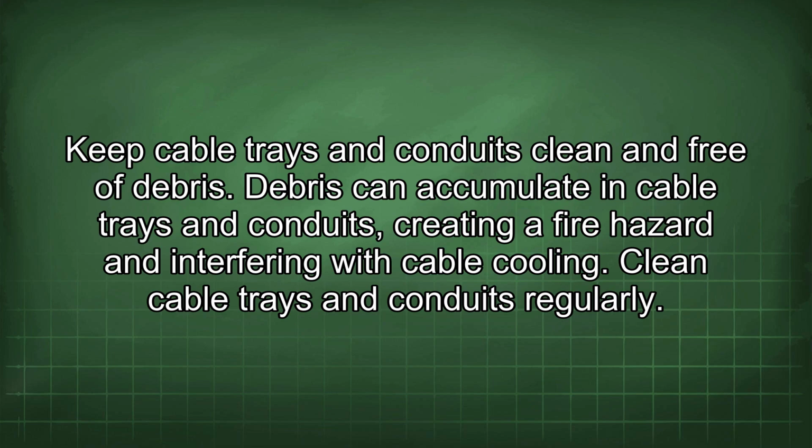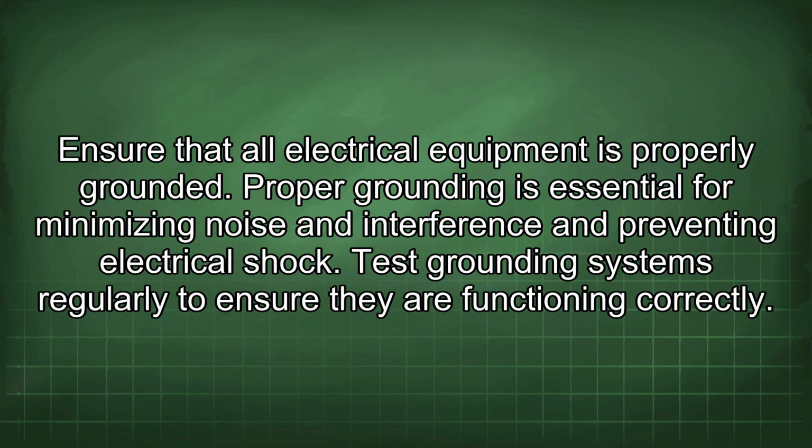Clean cable trays and conduits regularly. Ensure that all electrical equipment is properly grounded. Proper grounding is essential for minimizing noise and interference and preventing electrical shock. Test grounding systems regularly to ensure they are functioning correctly.